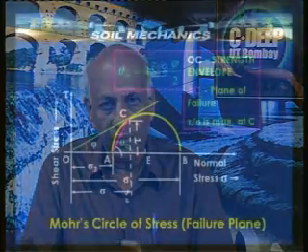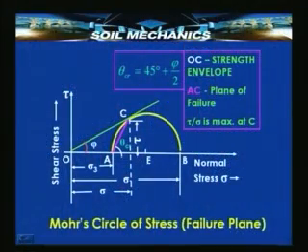So, we incidentally also have a criterion which is obvious from here, that is tan phi, tan of the angle of obliquity with its maximum value, is equal to tau upon sigma. So, tan phi equal to tau upon sigma, or tau equal to sigma tan phi, becomes the criterion defining failure.